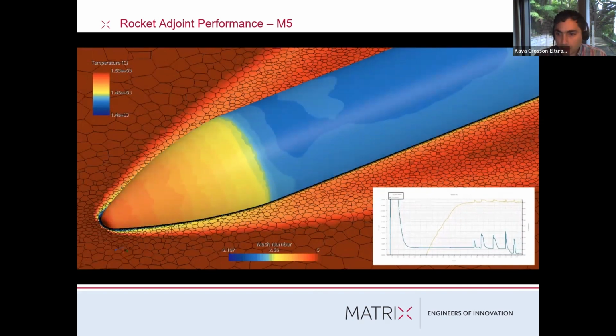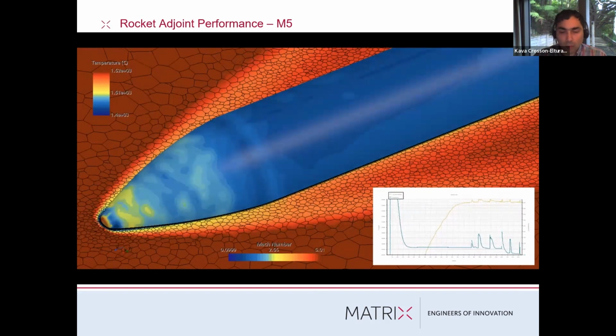that solution. So I also tried to run a case here where I base the adjoint optimizer on an objective function of average temperature, so minimizing the average temperature at the surface of the rocket, but that didn't go so well. I think numerically there were just problems there with deriving the adjoint connection between the temperature field and the temperature average and the aero surface shape.